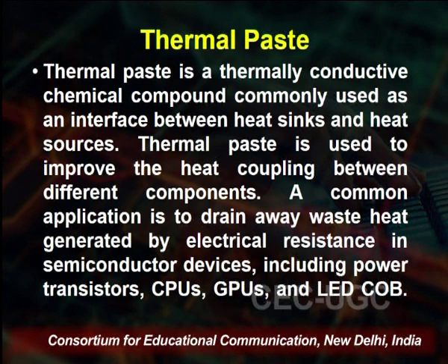Moreover, in this thermal conductivity, we have one of the options, which is thermal paste. Thermal paste is a thermally conductive chemical compound commonly used as an interface between the heat sink and the heat source. This paste can be used for cooling, and it is used to improve the heat coupling between the different components. A common application is to drain away waste heat generated by the electrical resistance in semiconductor devices, including power transistors, CPU, LED and COP.